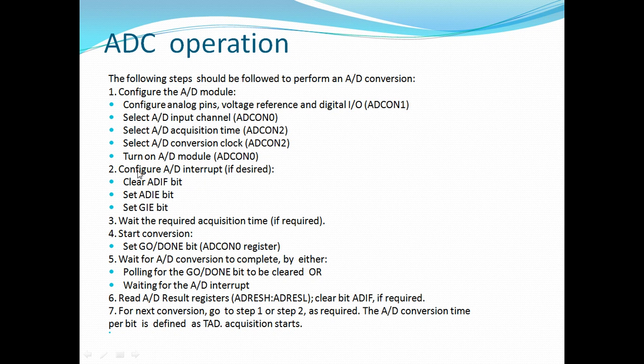Now to allow this interrupt, we need to set these particular bits: the ADC interrupt enable bit and the global interrupt enable bit. These two bits should be used in set mode.